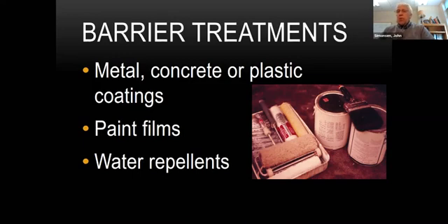Generally, the water repellents, well, it's what they say, they're repellents, right? So they don't eliminate water. And typically high humidity can raise the moisture content in the wood higher than we want, higher than the 20%, which is our standard guide, because humidity will penetrate the water repellents.